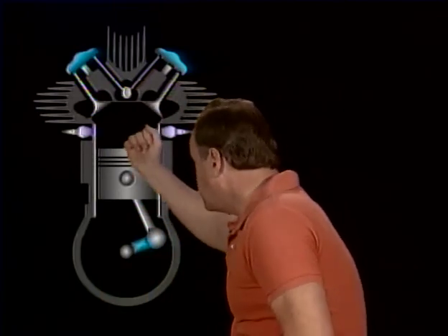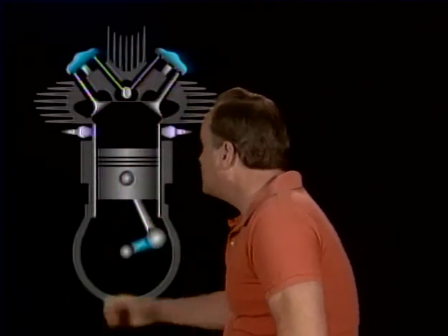And the reason you wouldn't get any reading at all is that when the piston's at bottom dead center, the exhaust valve is open. At least one valve will be open. And so the test cannot be made with the piston at bottom dead center. How about that? All right, how often, they ask on the test, should cylinder compression be checked?